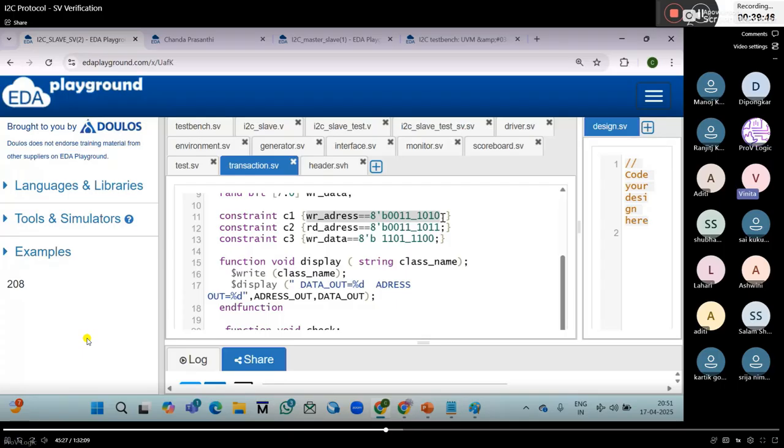One quick question, Prasanti, just on this topic, then on constraints. If we use a constraint called unique or something like that, then we can't use randc, right? I was getting a compilation error saying with unique you can't use randc. Is it some limitation on randc? Actually, randc generates values only within the loop, and it doesn't repeat any value.